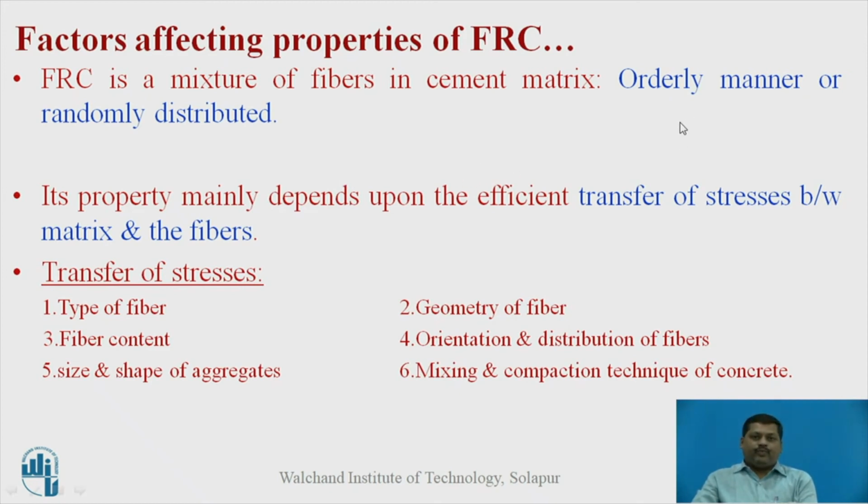Now first factor is the fibers may be in an orderly manner or randomly distributed. This is the first factor. If proper distribution is there, definitely the properties of FRC will increase. Second important factor is transfer of stresses between matrix and the fiber. Whatever load or stresses are coming on the concrete, if all these stresses are effectively transferred from matrix to the fiber, then definitely your properties will enhance.